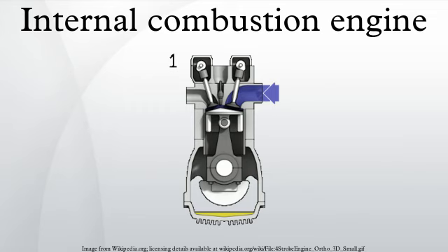It should be noted that the piston has 3 functions in its operation. The piston acts as the combustion chamber with the cylinder and compresses the air-fuel mixture, receives back the liberated energy, and transfers it to the crankshaft. The piston motion creates a vacuum that sucks the fuel-air mixture from the carburetor and pushes it from the crankcase to the combustion chamber. The sides of the piston act like the valves, covering and uncovering the intake and exhaust ports drilled into the side of the cylinder wall.